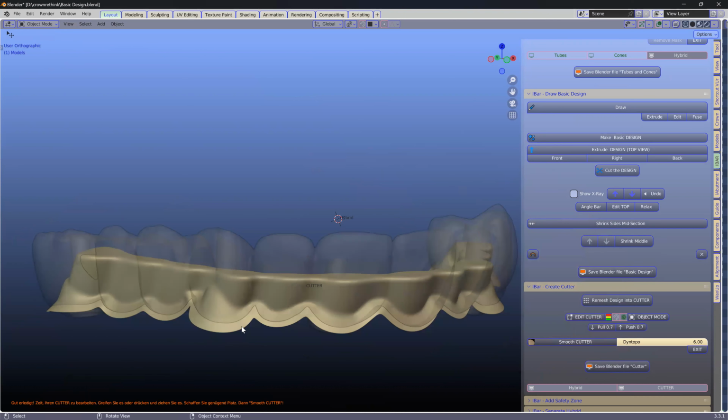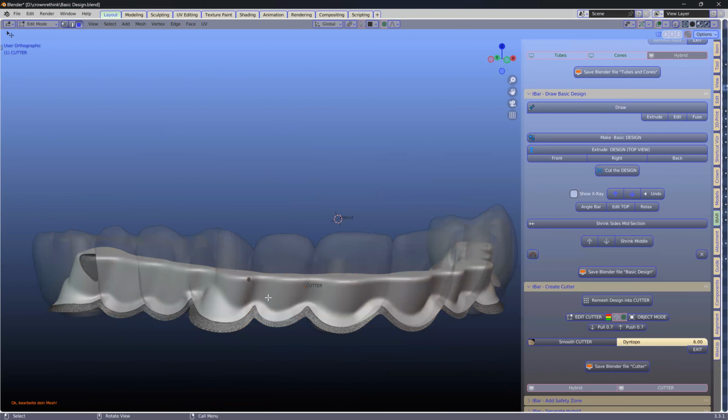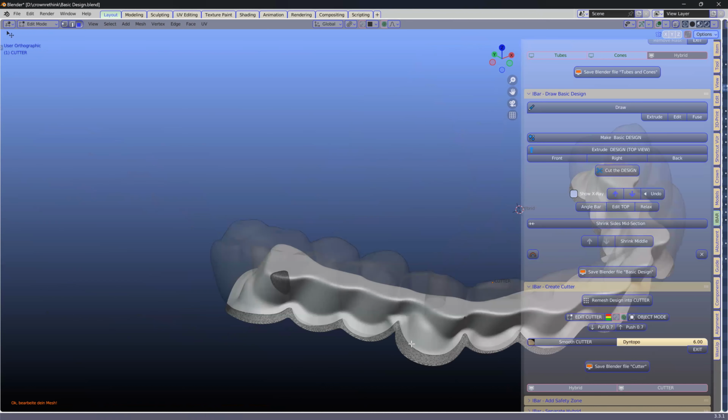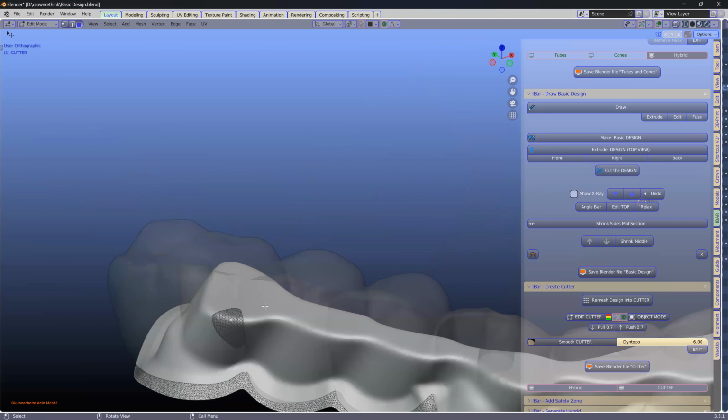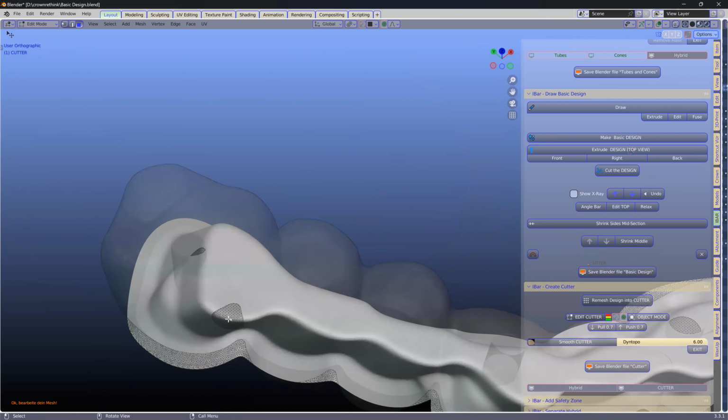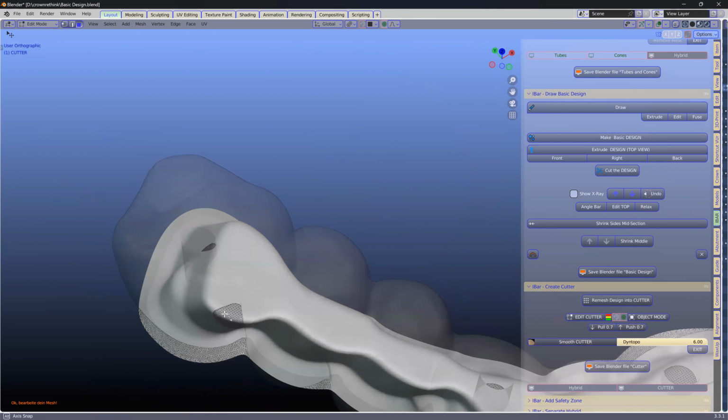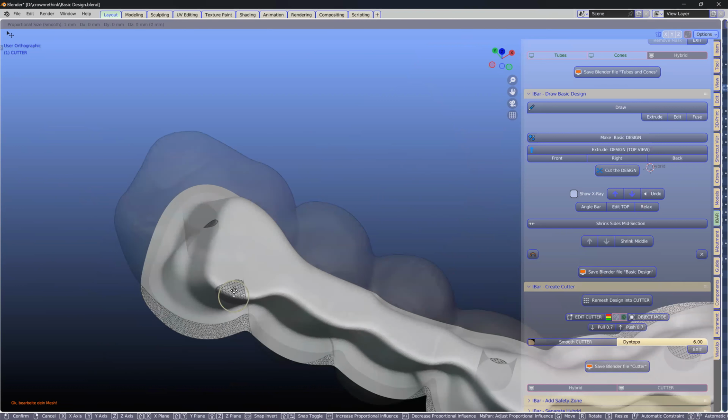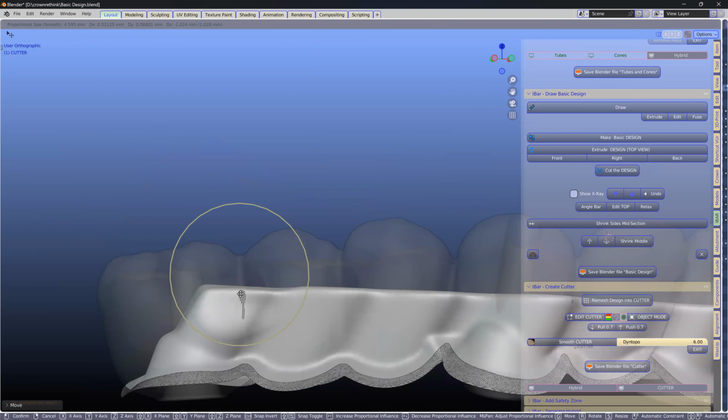Okay. Now you're going to select it and you're going to go to edit. And in edit mode, we can see, here's a problem. Now we need to reach a compromise between putting mesh geometry on the outside or moving this cutter on the inside. So here, what I'm going to do is move it on the inside. I'm just going to look at it from the top, and then we're going to use the G key and the mouse wheel, which we call proportional editing. That's that little icon up on the top, and we can manipulate this mesh.